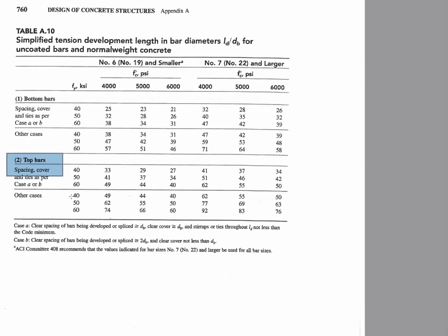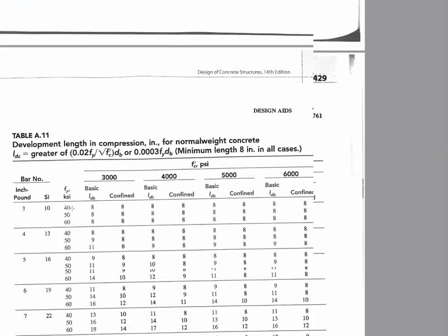So it would actually come up in between 2 columns and go upward a little bit. Not a real dramatic curvature on that, but curvature nonetheless. And with that concave downward curvature, you're going to have tension on top. And that's why you may have steel on the top of a footing, by the way.